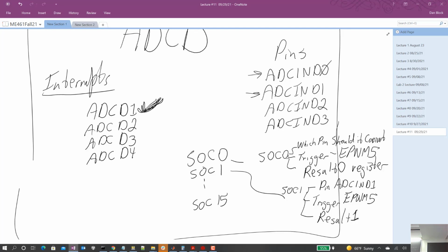Now I could have chosen to use CPU timer 0, CPU timer 1, and CPU timer 2. Remember, we've been using all 3 of those, and they generate an interrupt right now, don't they? And we've got an interrupt function that's using them. I could have chosen that, and it probably would work great. For your labs, you could get by with just 1 or 2 timers probably. But I decided the PWM's not used for anything. Maybe you could think about ways you could use all 3 of those timers in your design for your code. Anyway, you could choose.